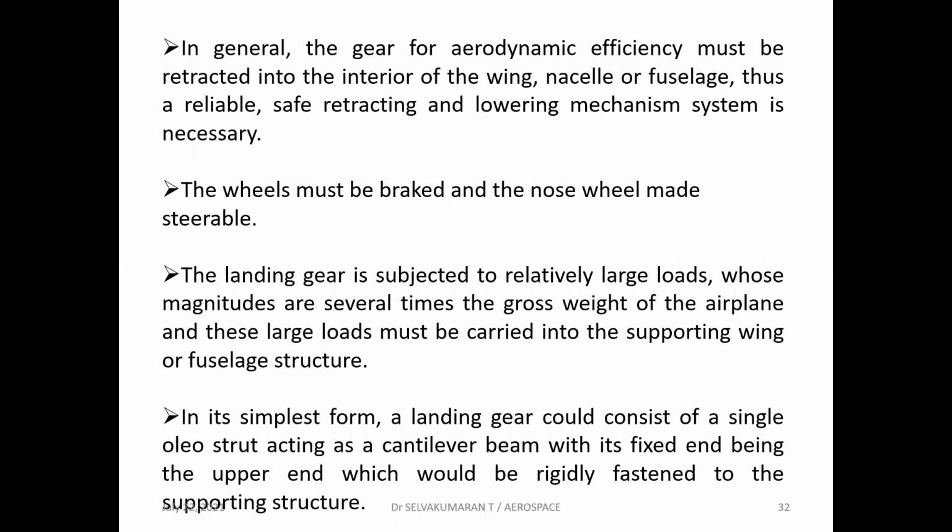The wheels must be braked and the nose wheel is made steerable. The landing gear is subjected to relatively large loads whose magnitudes are several times the gross weight of the airplane, and these large loads must be carried into the supporting wing or fuselage structure.